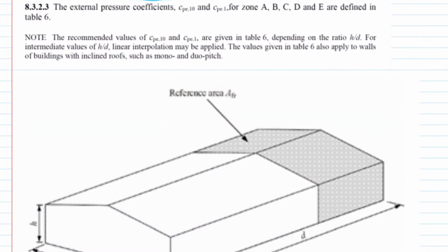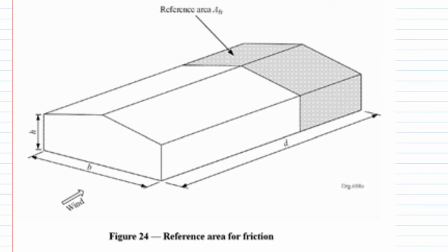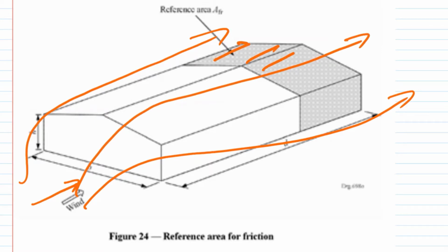And so one thing we have skipped, and this is just more a backtrack to tell you that this factor exists, but we're ignoring it just because we don't have time and scope in this course. But please don't ignore it in real buildings, especially on bigger buildings. When the wind blows across the building, you then have wind blowing around it. You create friction along the surface. And this friction you should design for, especially in your lateral load resisting systems.